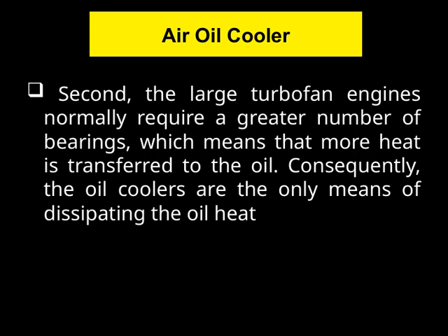Now, moving on to the next point, it's important to understand that large turbofan engines typically require more bearings. This is mainly because these engines are bigger and handle more power, so they need additional support to keep everything running smoothly. However, having more bearings also means more heat is generated and transferred to the oil. As a result, managing this heat becomes crucial to maintaining engine performance and reliability.